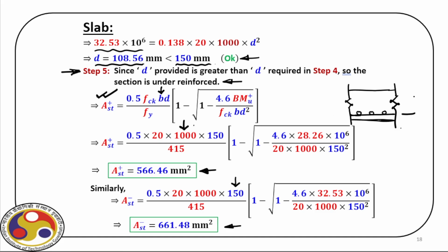Okay, so for main rebars, this is the depth. If need be, we can actually modify this, but for the time being, we use the same value, which is 150, right? So whether it is mid-span or over the support, we have the same. As we go in the two-way design, we'll see we'll use a different value of D, because for the other bars, it is somewhere here.